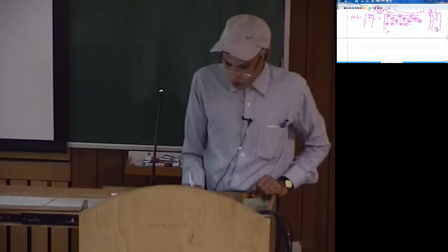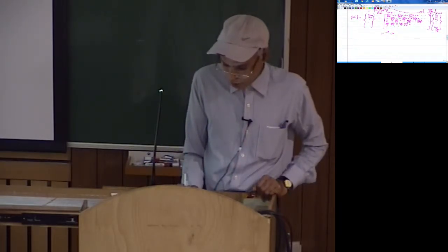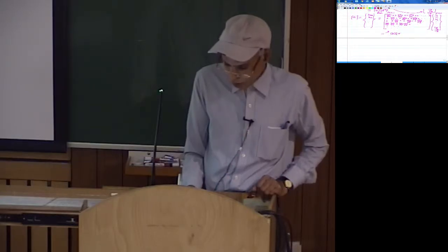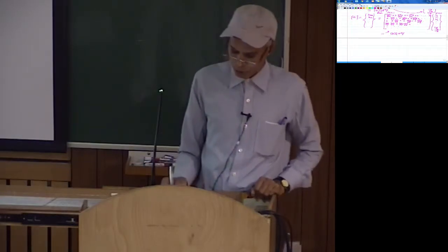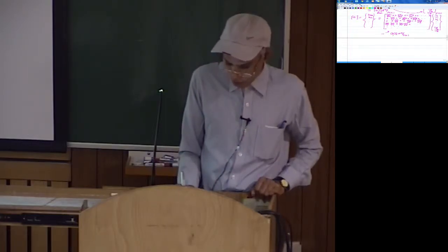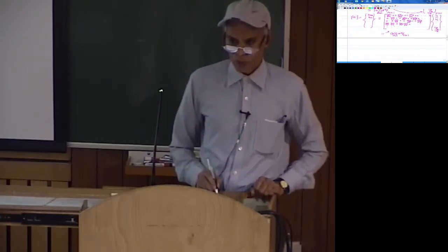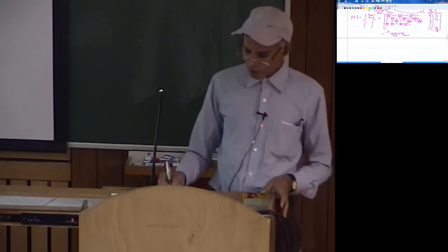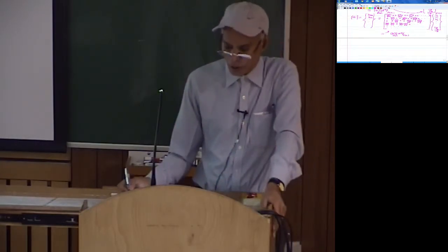So this is what we call the strain displacement matrix B, into the vector of elemental degrees of freedom. You will find again this is 24 by 1 and now B here is 6 by 24, right. So B is your strain displacement matrix.